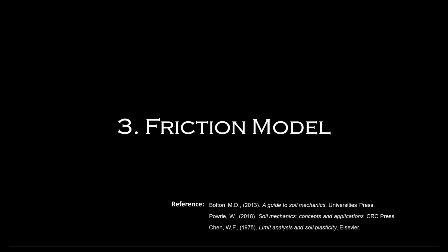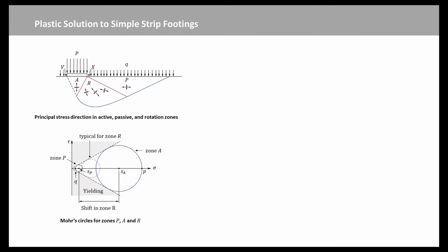Next, we will analyze the friction model to estimate the bearing capacity of the strip foundation. This figure shows our conventional representation of a 1 meter length of strip footing, which is supposed to receive no benefit from adjoining sections. Therefore, it might be taken out of an endless footing. The stress between footing and soil has been increased to P, at which point the overburden pressure Q is pushed into the air and the footing collapses.